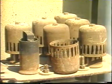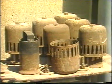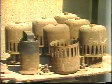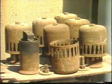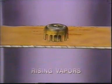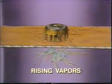Different types of internal hardware are used to control the downward flow of liquid and upward flow of vapors inside distillation columns. The purpose of this hardware is to maximize the vapor-liquid contact which is necessary for good fractionation to occur. This bubble cap has teeth or slots that are set below the level of the liquid on the tray. Vapors rising through these slots are broken into small bubbles before they pass through the liquid. By forcing the vapors to form small bubbles, the surface area for vapor-liquid contact is increased.